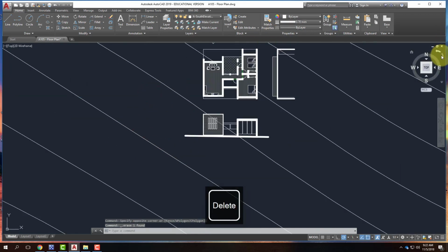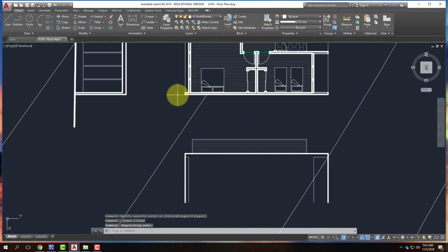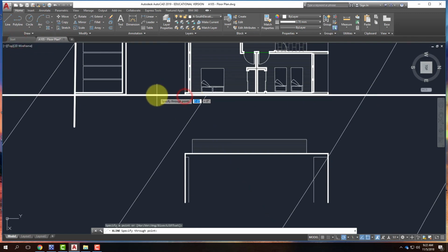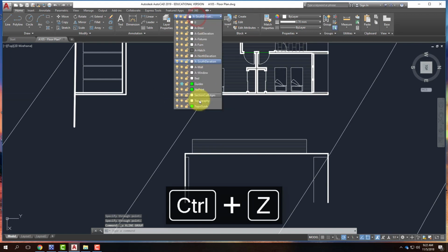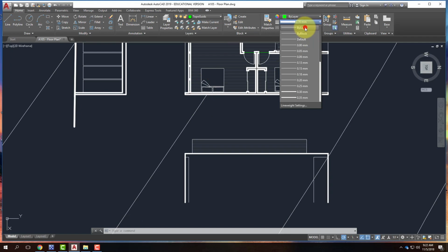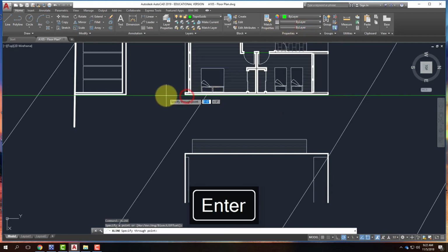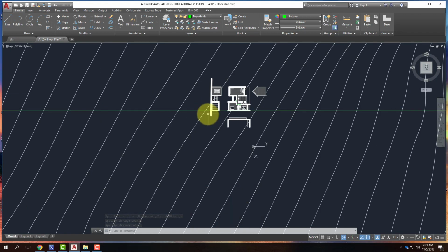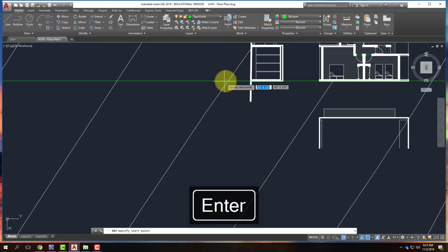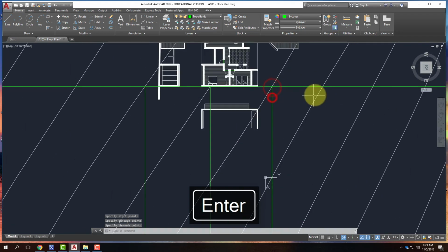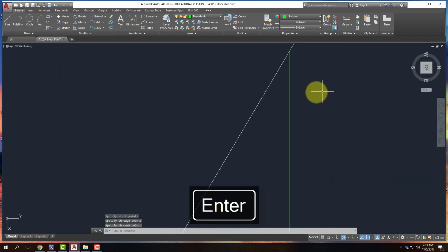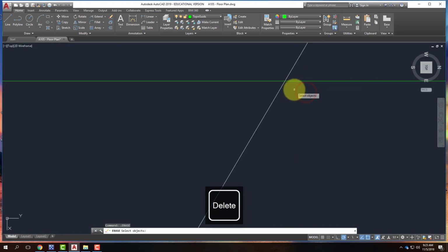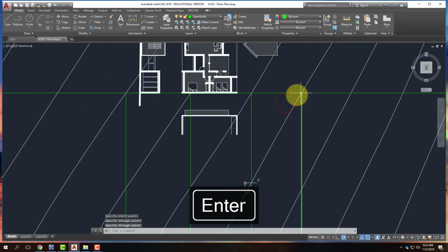And for the next building elevation, when I rotate my building, I'll create a line that goes along this face. So once again, it'll be an X line. Like that. Oops. Sorry, I should have been on the guides layer first. And there it is. That's the plane. I need to identify the intersections. So once again, I will go to my ray command. Oops, didn't quite get that. Oops, ray. Okay, so same process, X line.